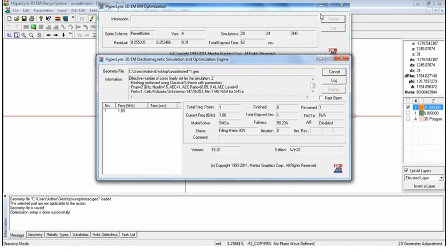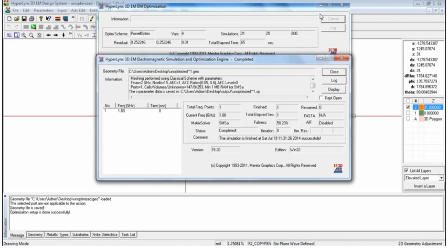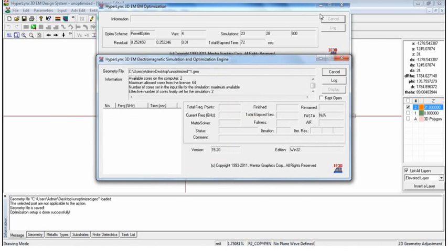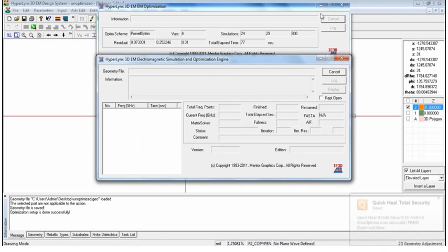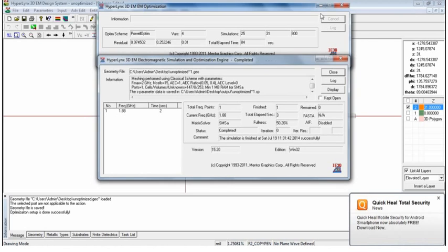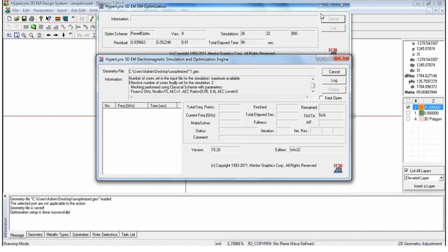Also, one more feature of IE3D is that you can do this simulation or optimization in real time. That is called the fast EM kit from IE3D, where I can manually slide those variable sliders and see the graphs, or I can tune the graph. So automatically it will change the geometry as well as the graph. So I can fit the geometry for that particular response.